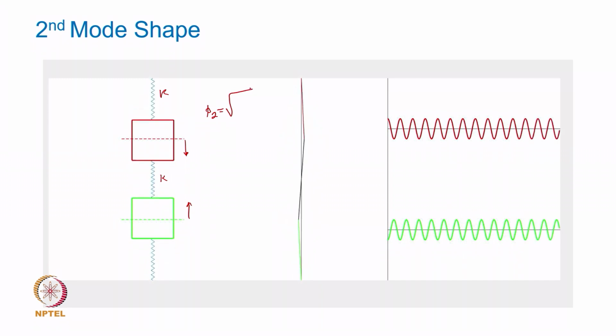the strain energy stored in that spring is going to contribute, right, and the strain energy is half k x square, which means that it will contribute to the numerator. This spring does not have any mass, that is our assumption. So, the moment the strain energy of the system is increased, your natural frequency is expected to increase. So, the moment 3 springs are now effectively contributing in the vibratory motion, we expect the second natural frequency to be much higher than the first one.